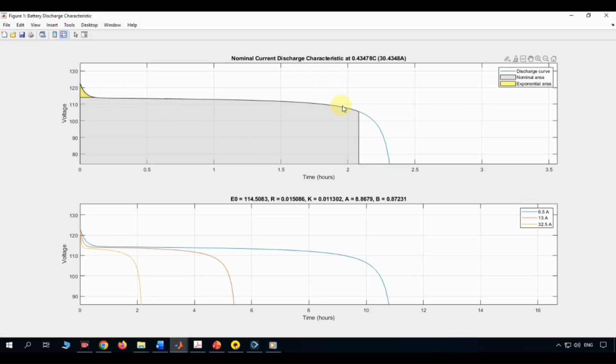The blue discharge curve tail, the steep final drop as the battery approaches full depletion and hits the cutoff voltage. This three-region shape is the signature look of a lithium-ion discharge curve, and it's exactly what the model reproduces using the parameters we just went through.